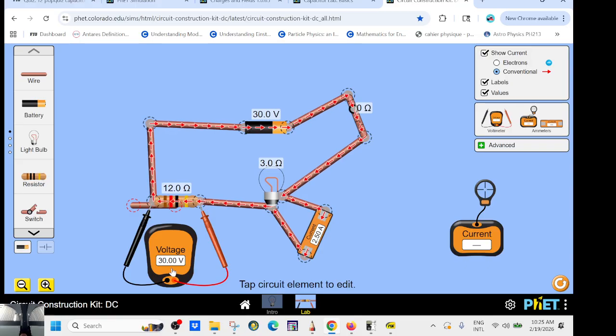Now, with voltage, you don't want to make a short, so a voltmeter will have a very, very large resistance. It will be the opposite. A voltmeter will have a large resistance, so nothing can be deflected. Some will, because you need to do the measurement, but otherwise you have to use another technique to measure the voltage. But very, very large resistance, right?